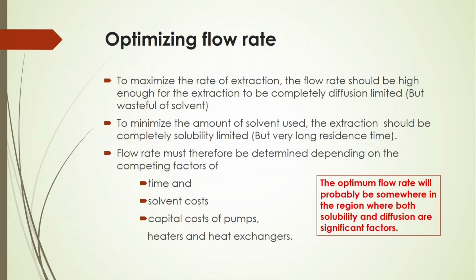You can also design the system based on the optimization of the flow rate. To maximize the rate of extraction, the flow rate should be high enough for the extraction to be completely diffusion limited, where wastefulness of solvent is the main concern. To minimize the amount of solvent used, the extraction should be completely solubility limited, but very long residence time is one important shortcoming.